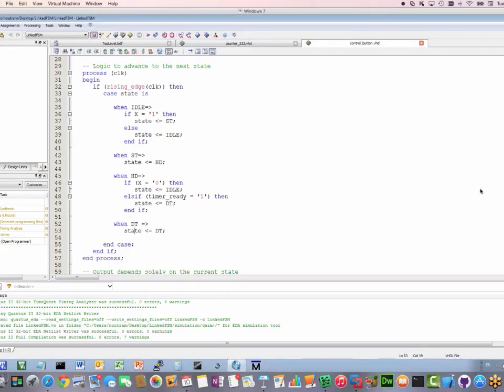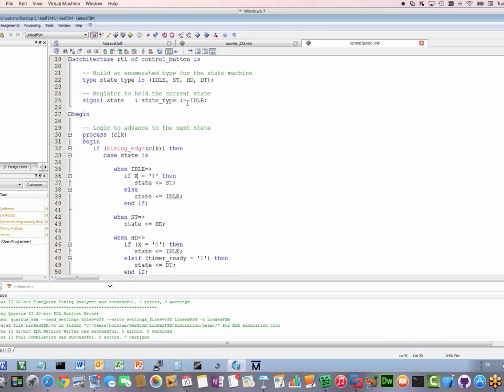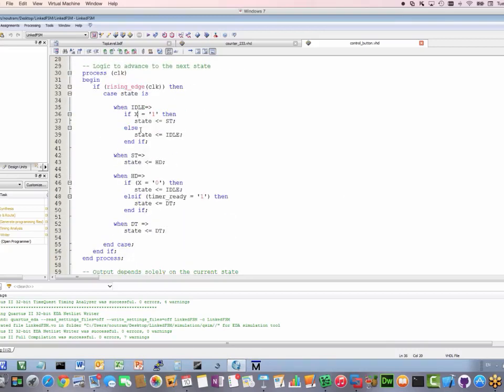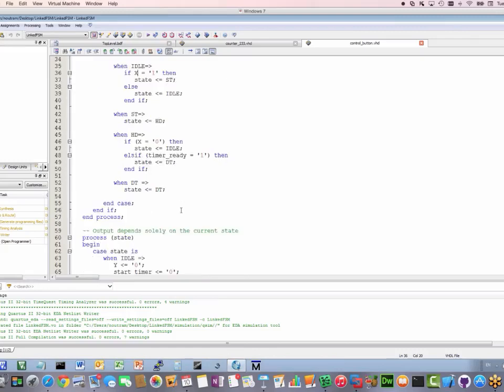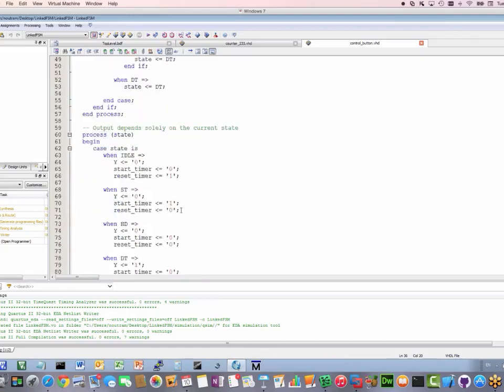Question coming in. Okay, it's interesting you asked that. In VHDL, is there any point in reducing the amount of states if integers are stored as a 32-bit number anyway? Aren't you using the same amount of D-type flip-flops? Right. Because I've used an integer for my state, I've only got 4 states. It should be able to work that out and encode them as a 4-bit number.